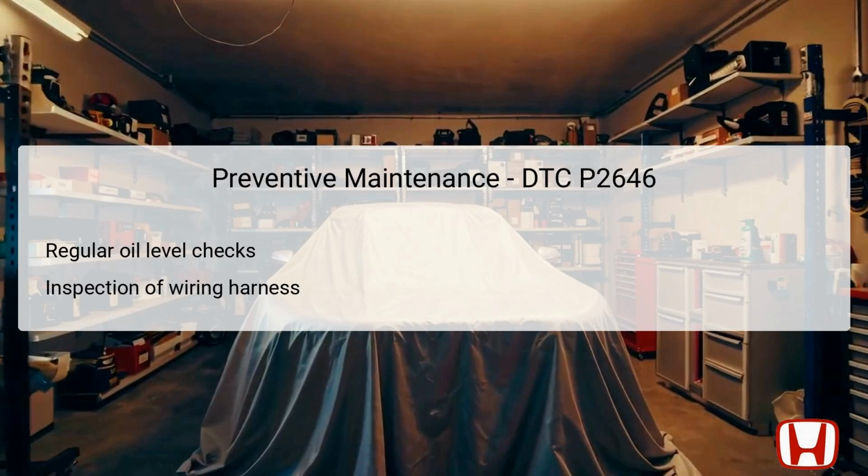Regular inspections of the wiring harness connected to the rocker arm oil pressure switch are equally important, as any signs of wear, fraying, or disconnection can lead to the DTC being triggered unexpectedly. Vehicle owners should be educated on the importance of timely oil changes, as clean oil is crucial for proper lubrication of engine components.